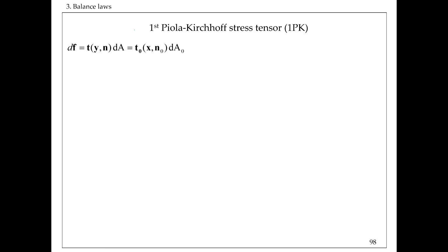To start from something very trivial, we have a small force element, the resultant force acting on a small area element, dA, and through that we introduce the traction vector, which is the force divided by that area element. And this is how we would do that in the deformed state.